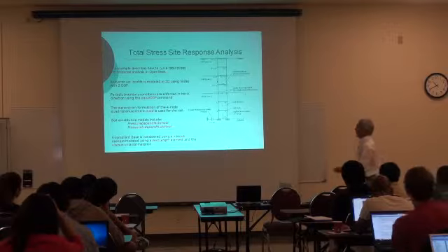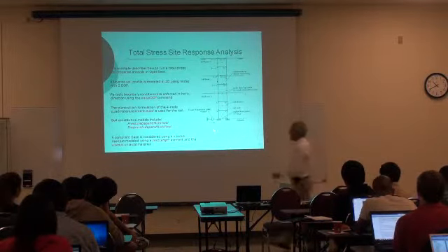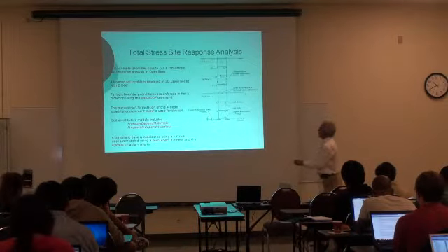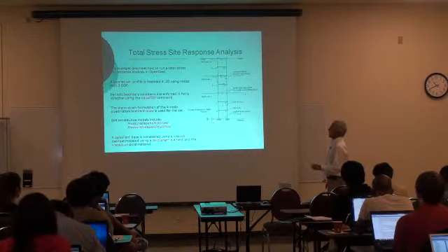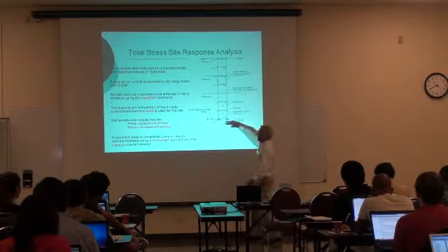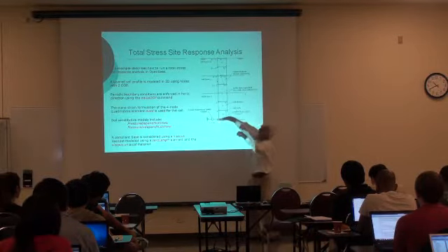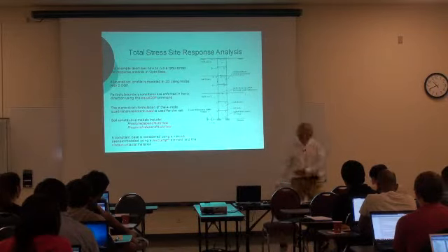We use the pressure-dependent multi-yield and the pressure-independent multi-yield to represent the soil behavior here. And we also use a dashpot here and a viscous material in order to capture the compliant base. Sometimes what you want to model is the soil behavior up to the rock. But then the rock may be a soft rock, and you want to include the response or the effect of the soft rock.